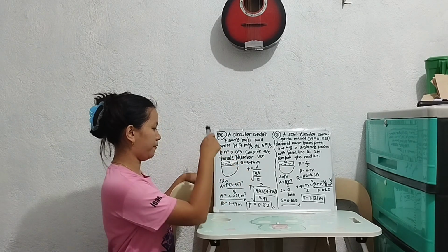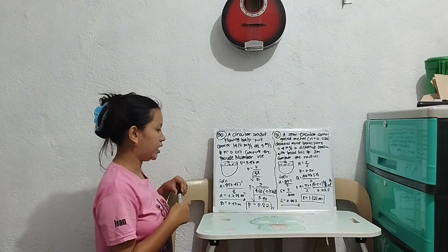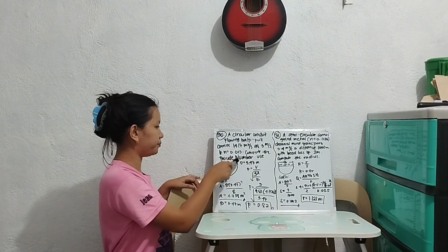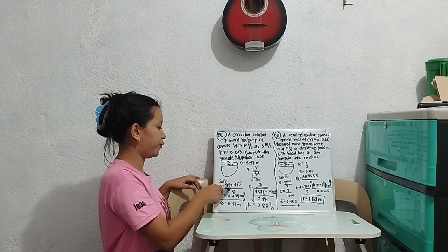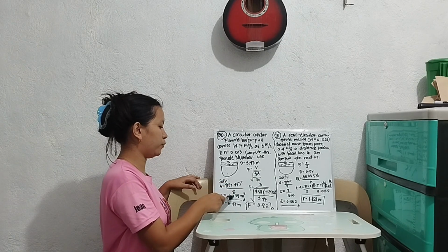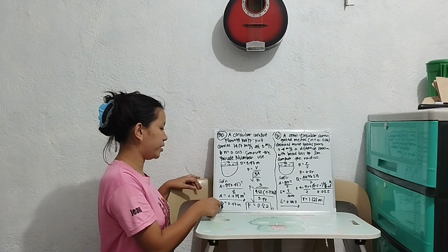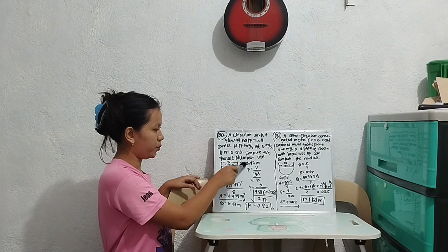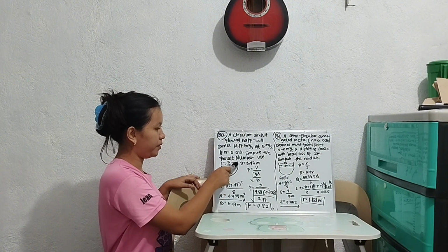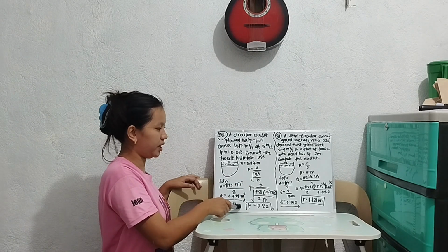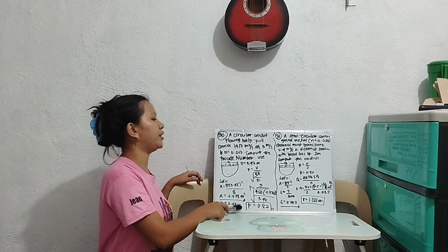So first we need to find the area. So pi times 3.47, which is our D, squared over 8. So area is equal to 4.728 square meters. And then our B is equal also to the diameter, which is 3.47 meters. So we need to find the Froude number.